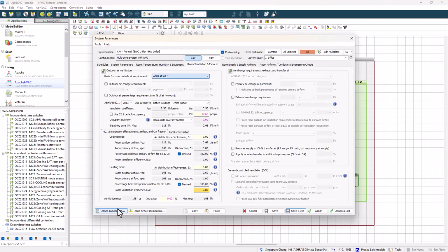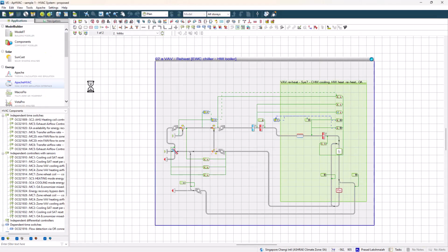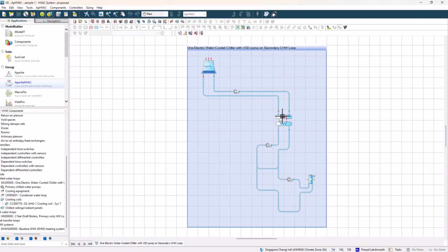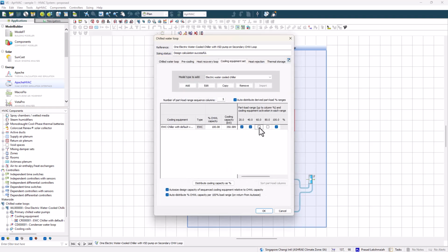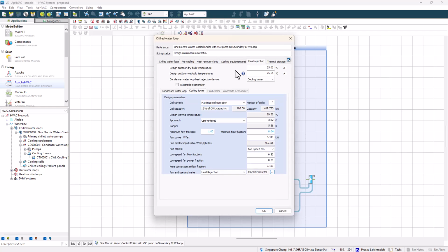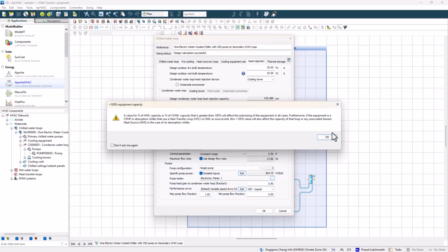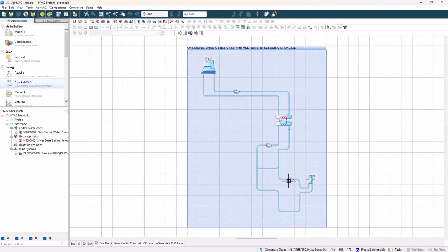We can also import predefined settings from the library as we work, for example, the chiller performance curves. The HVAC system is laid out graphically with component parts and controllers, which can all be customized to suit. The systems are then linked back to the spaces and zones of the model geometry. We can edit the system parameters with reference to ASHRAE standards, such as occupancy classes.